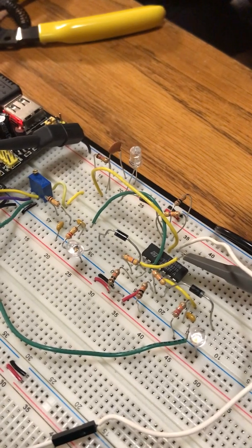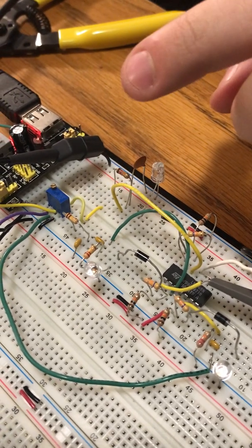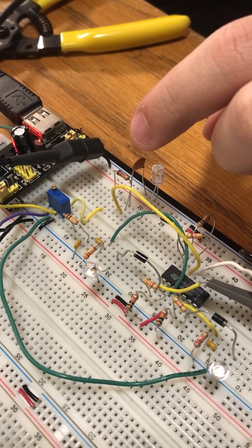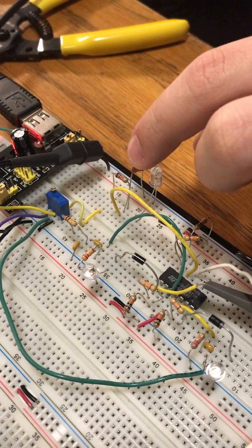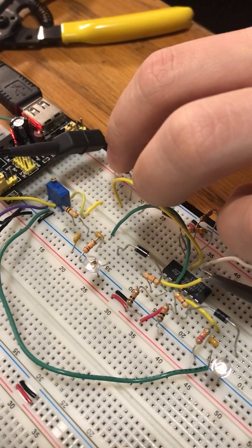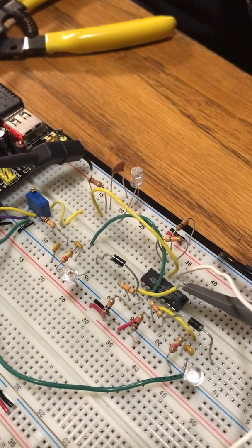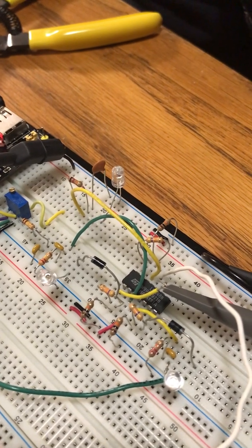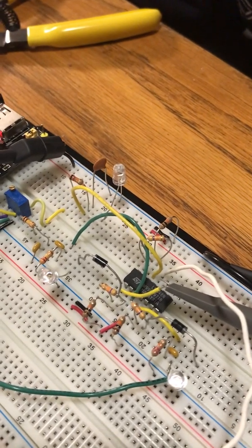Let's start with the low pass filter. Low pass filter is over here. We have a resistor of value 12 kiloohms. It's a 12 kiloohm resistor with a 0.1 microfarad capacitor going to ground. So that resistor gets the signal, and it has a 3 decibel cutoff frequency of approximately 125 hertz.